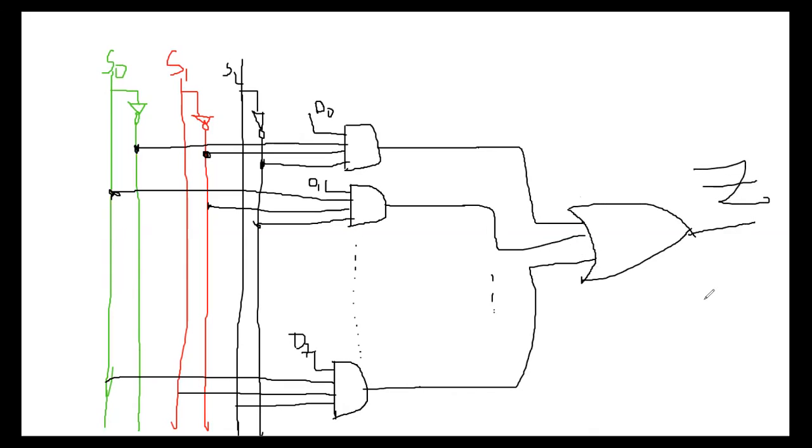So like that, we can draw the logical diagram of the 8x1 MUX. We already saw the 2x1 MUX, and it requires 2 AND gates, 1 inverter and 1 OR gate. And the 4x1 MUX we already saw: 4 AND gates, 2 inverters and 1 OR gate. And the 8x1 MUX requires 8 AND gates, 1 OR gate and 3 inverters. Following, my dear students.